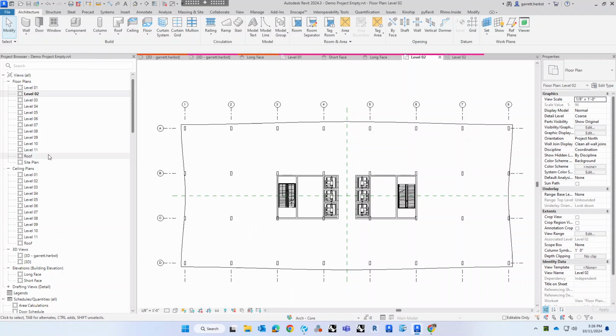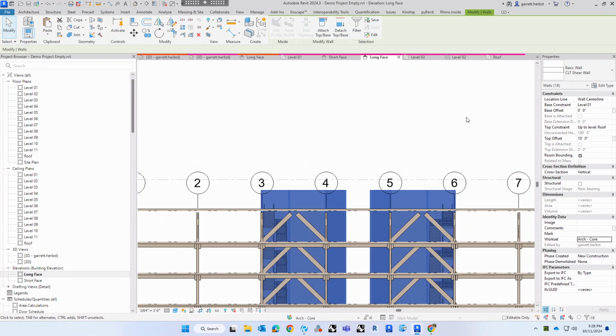Your big equipment typically will live outside the core, but your electrical equipment and a lot of your plumbing infrastructure, especially in taller buildings like this, will all be within an enclosed penthouse space, as well as your elevator machine rooms, your overruns, and then the stairs, right?